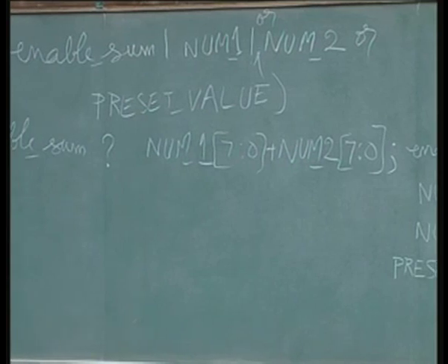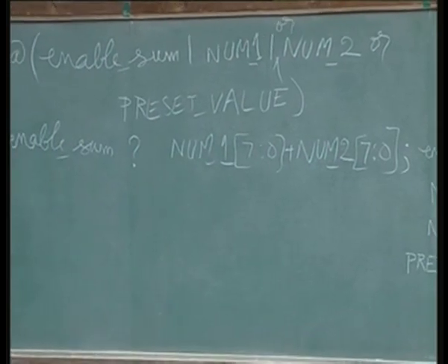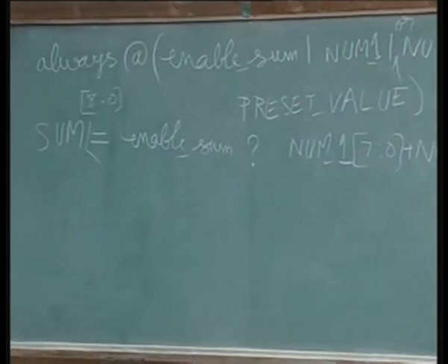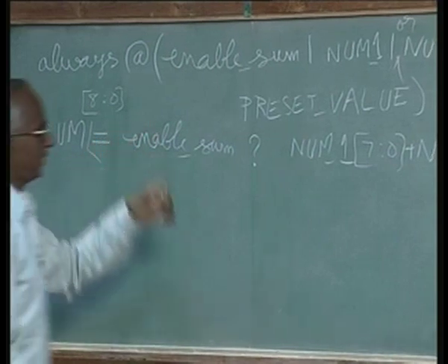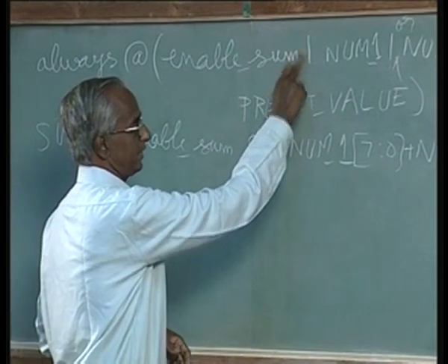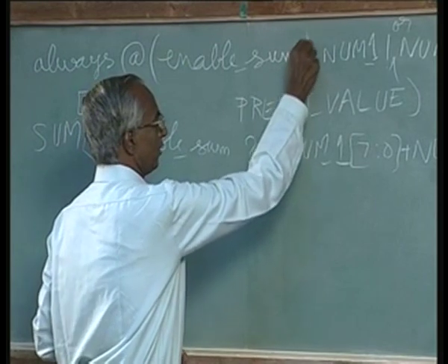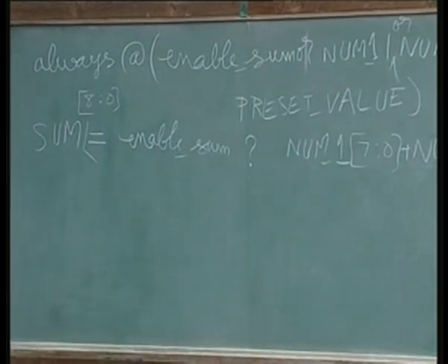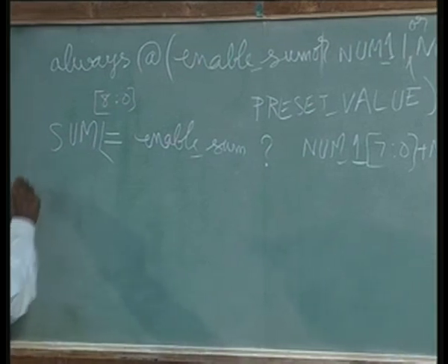And similarly, many people, especially novices, make the mistake of putting a logical OR here. This is not a valid thing. So, what we have to do is put a bitwise OR. And now similarly, we will write for the other three outputs, that is match.